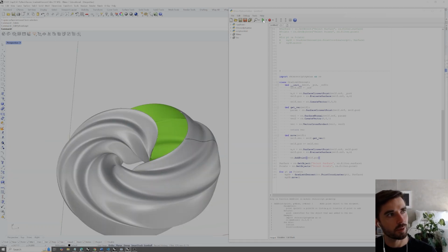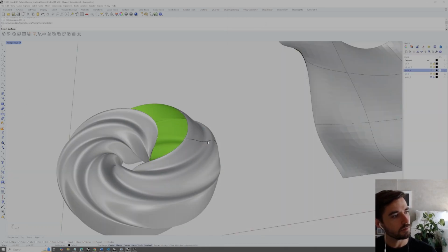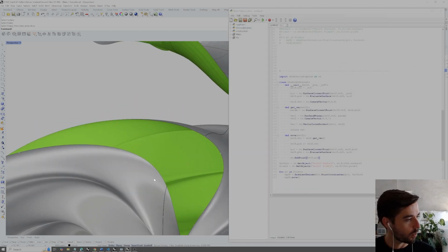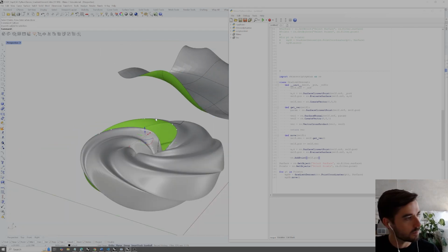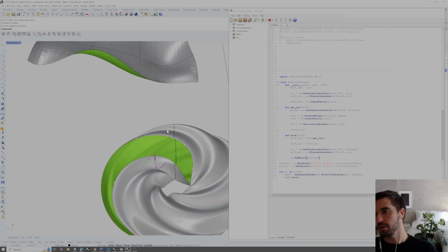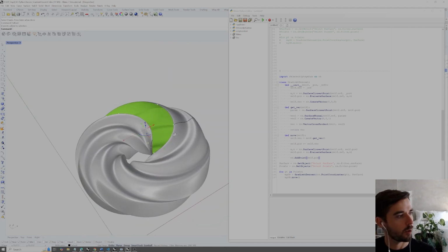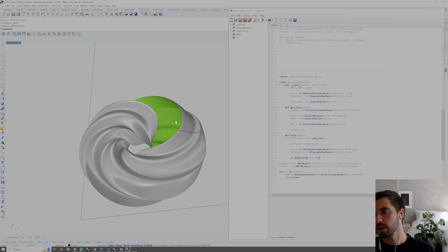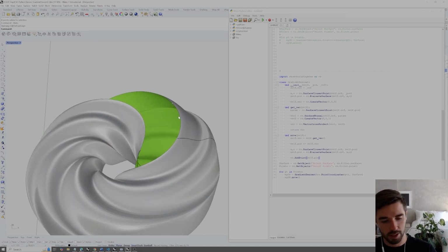So now if I click play, select our surface and then our points, we now get points drawn out. So we can see a few of those points drawn out and added to our document that are that cross product output, and then being snapped back onto our surface.